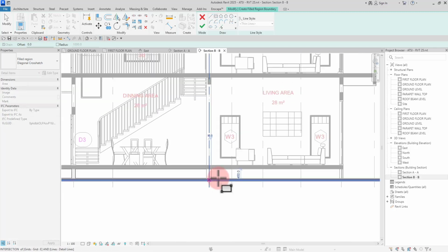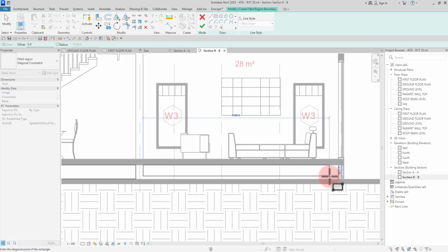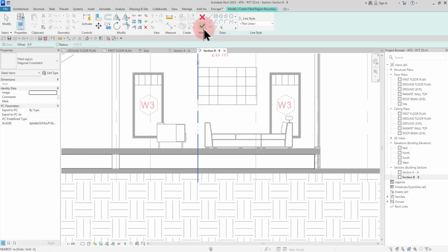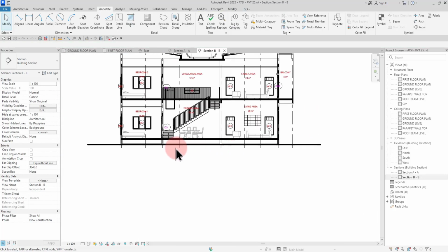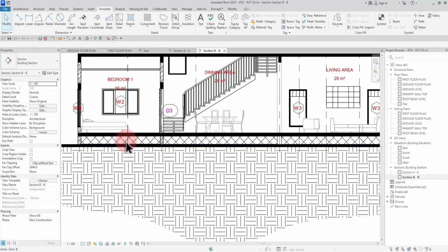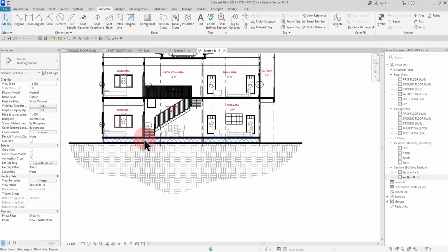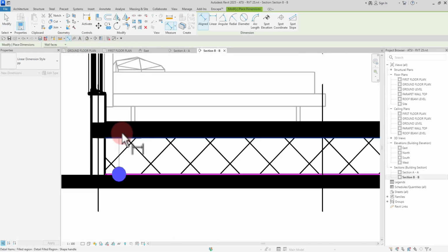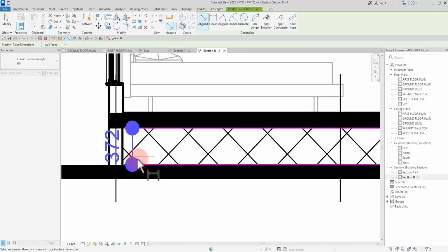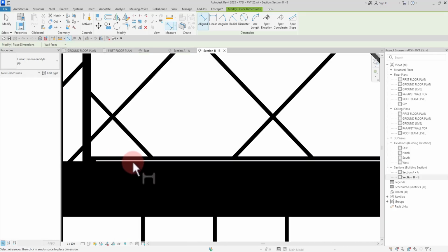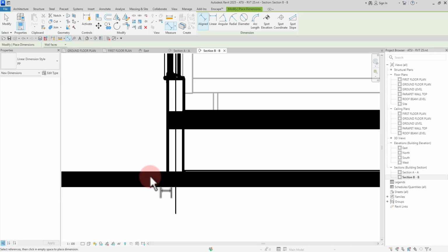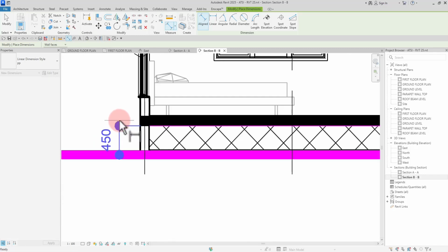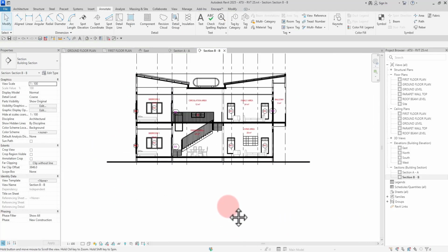We have a wall, a footing coming over there, so we are not going to do anything there. So we are not going to put in the cross. All right, so perfect. So we have all those hardcore hatches. That's our hardcore filling. All right, it's usually 450. So let me just measure that to see what we have in there. So it's exactly 450. It's just that the hatch didn't pick from the hatch itself. So we have that in there.